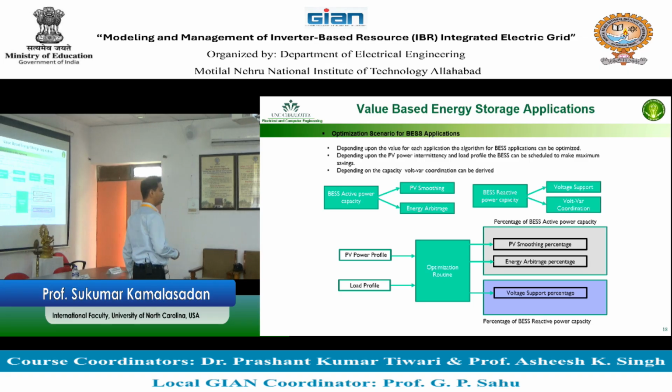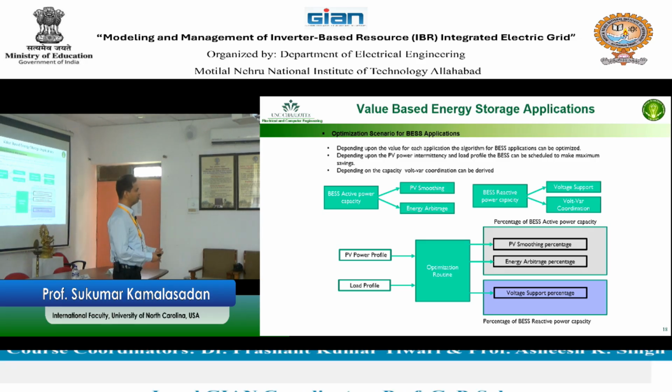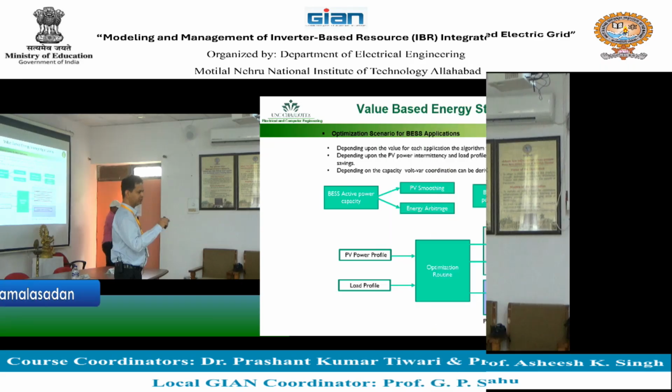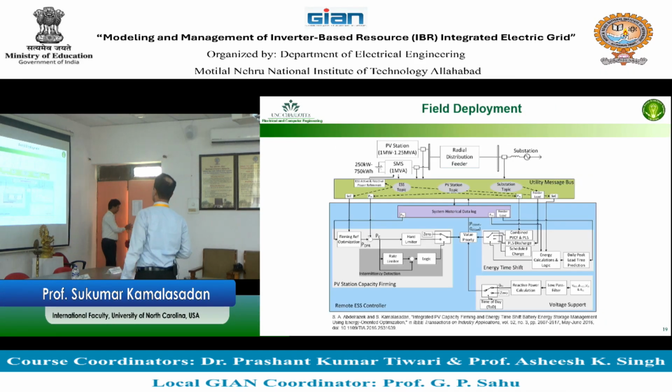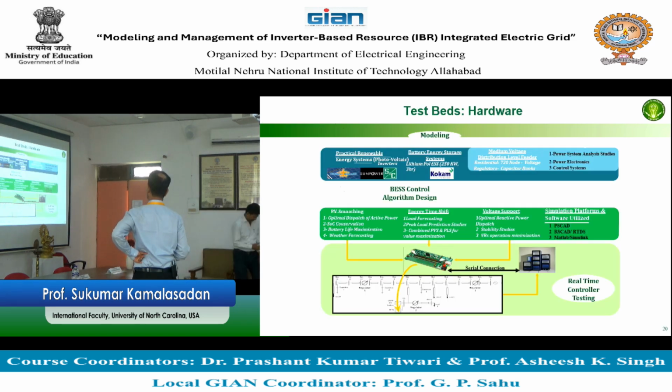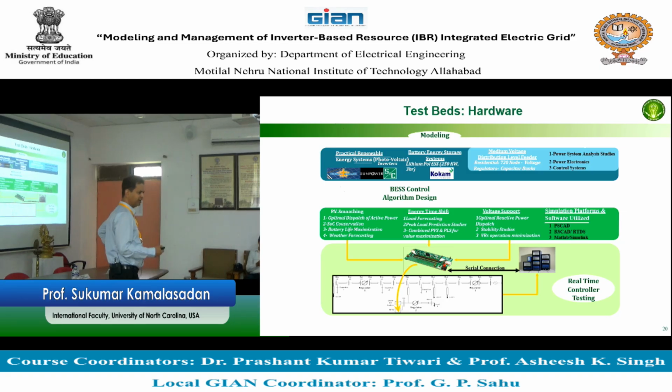Okay. So this volt-var regulation and volt-var control are actually mandated by the utility, and there is a standard curve that you have to follow, and the inverter follows that. So a smart inverter has volt-var control capability. You can push the button and the inverter will do volt-var control. It's possible. So here is an algorithm. We are not talking about that algorithm, but what we have done is we implemented this. By the way, this is implemented in the field and it's fleet-wide adopted.